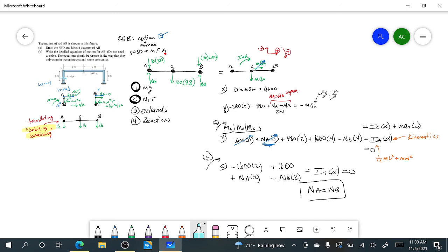And so that being said, free body diagram done, kinetic diagram done, and then you write your equations based on the pictures that you set up. So setting up this part right here, I would say, is the hardest. Setting up the free body diagram is not too hard. Just remember that sometimes you need to use kinematics to kind of build it. But then from there, setting up your kinetic diagram, it will wreck you. It's wrecked me plenty of times. And so be very, very careful.